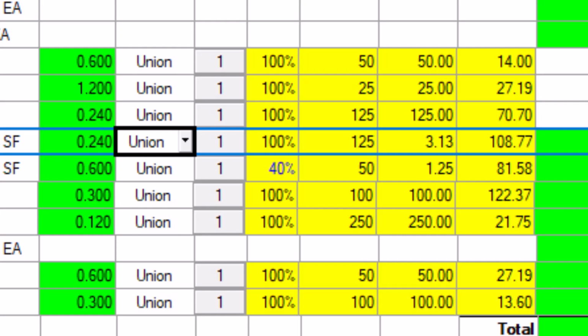Imagine you need to bring your costs down, and you think it's reasonable that your hanger can work a little faster. So you decide to change the percent base field to 120%. Making this change increases the quantity per hour and decreases the labor cost. However, be mindful that you're making decisions based on the capabilities of real people. Don't speed your production up so much that your crew can't achieve the rate in the real world just to get your costs down. Otherwise, you'll end up busting your budget anyway.